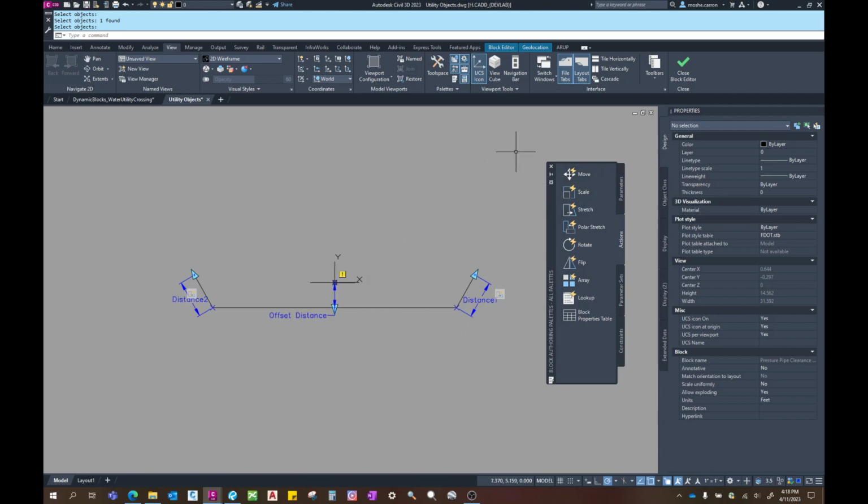I thereby allowed it to be moved from 6 inches to 12 inches. So in this case, again, select the parameter, specify the point, in this case, the point where I am moving, select the objects, and press spacebar. Now it has gone.